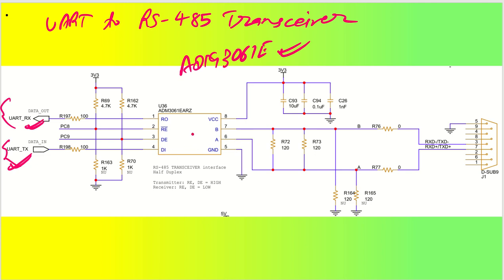It will act as both transmitter and receiver, based on the receiver enable and driver enable signals. Right now, both of them are pulled up by default, so it is acting as a transmitter.